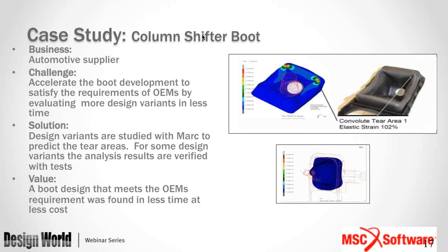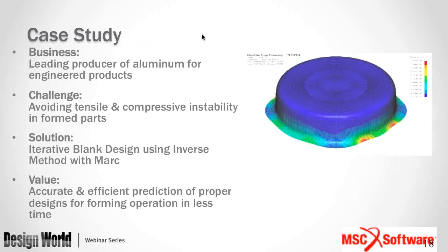So here, of course, there are several challenges. The material is nonlinear; it is elastomer, and there are several parts that are coming into contact. So MSC's MARC solution was used to solve this particular problem with contact analysis, and the various stages from the molded state of the boot to the various loading cycles are simulated in this analysis, and at the end they did meet the OEM requirements at much less cost.